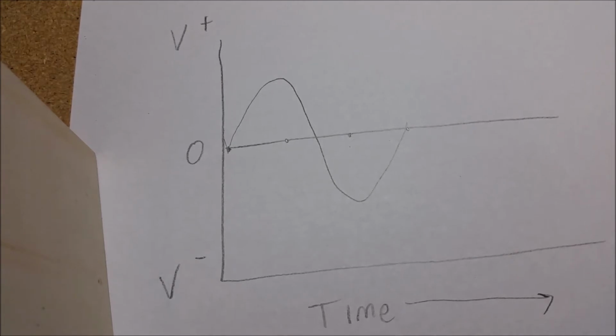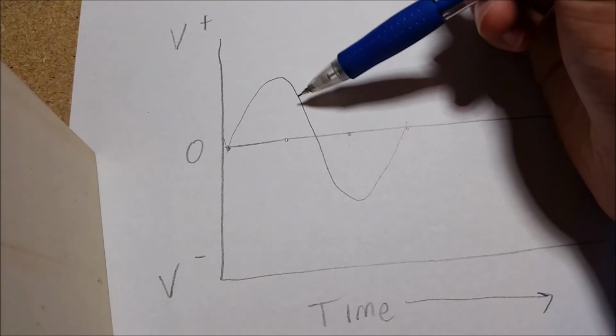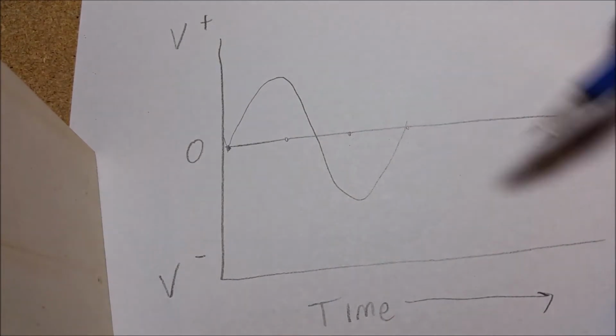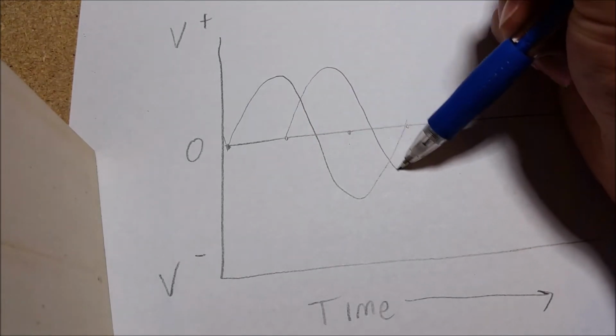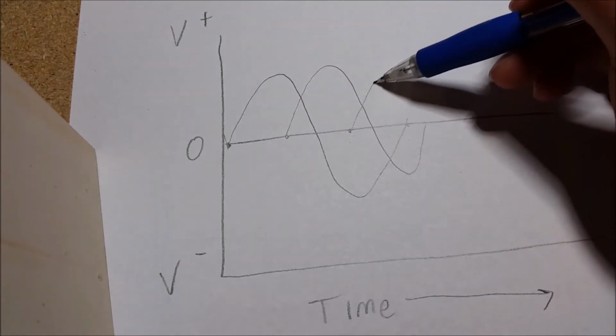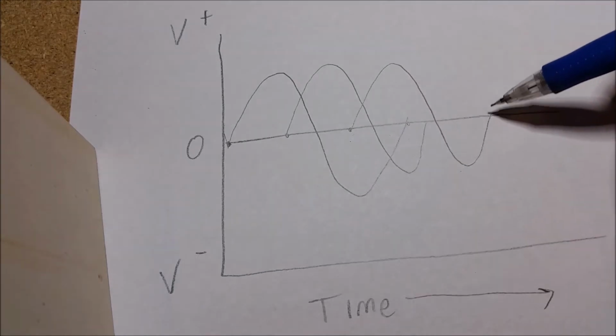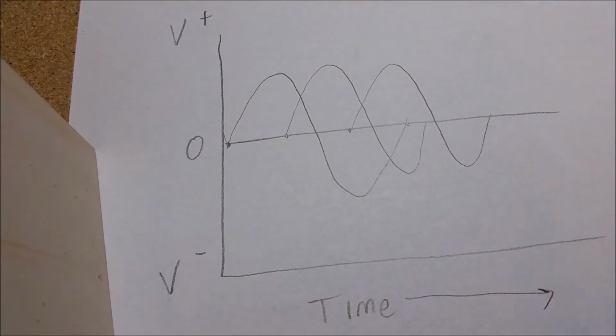But what I've shown you so far is just a single phase of alternating current. And it looks like this, it's just the sine wave from before. But because this is a three-phase stator, what is present is actually three sine waves. And so there will be three different alternating currents induced every time you turn the rotor.